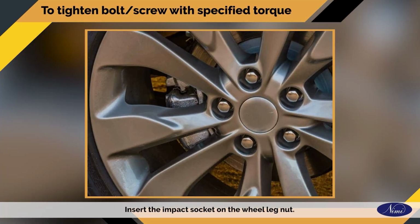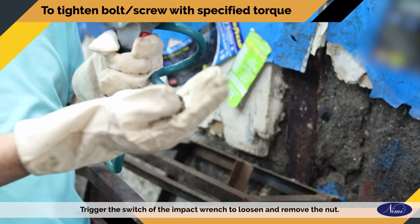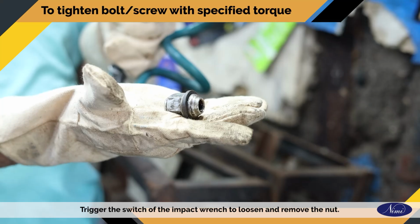Insert the impact socket on the wheel leg nut. Trigger the switch of the impact wrench to loosen and remove the nut.